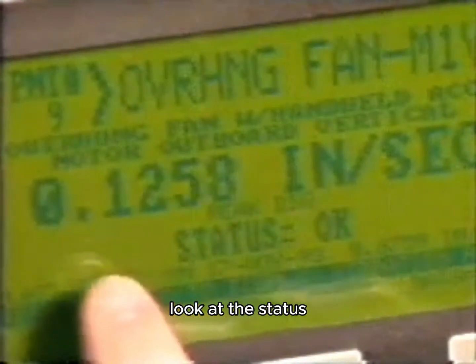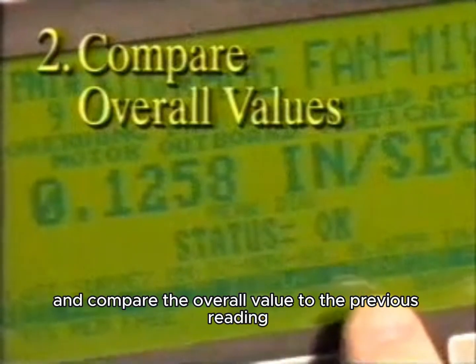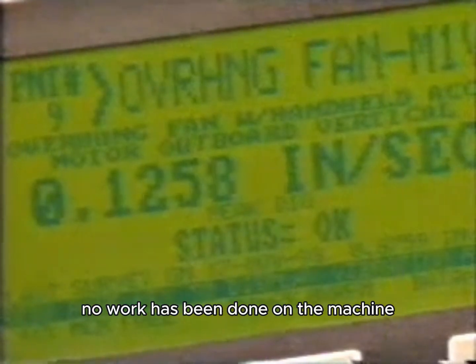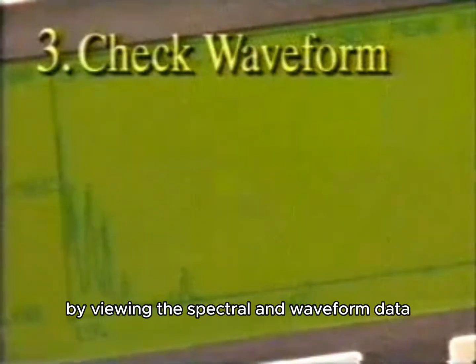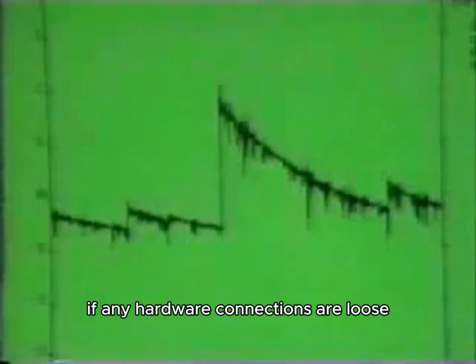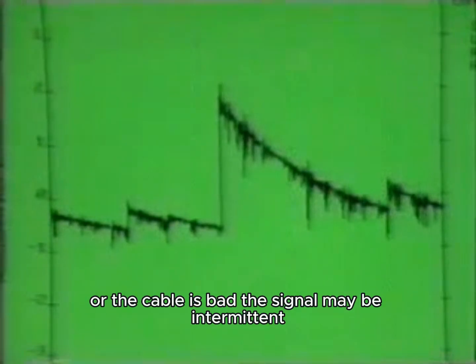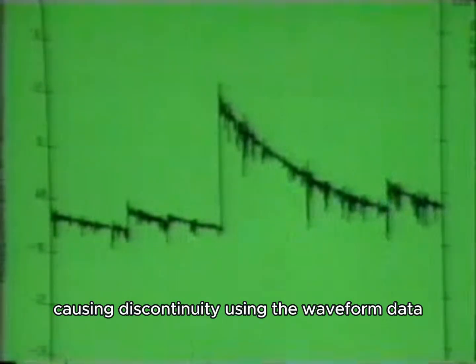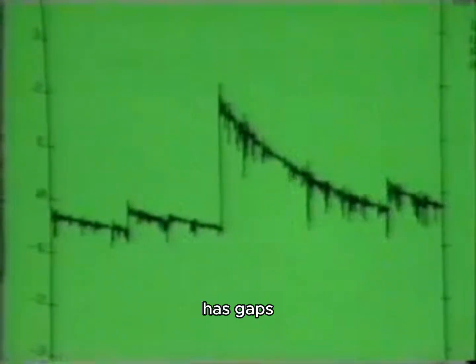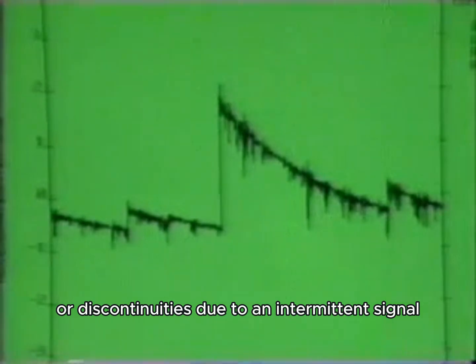Make the second check when a measurement point is complete. Look at the status and compare the overall value to the previous reading. The overall value for the previous reading is also displayed on the screen. If there is much disparity between the two overall values and you are confident no work has been done on the machine, then make the third check by viewing the spectral and waveform data, again looking for disparities. If any hardware connections are loose or the cable is bad, the signal may be intermittent, causing discontinuities in the waveform data. This waveform is typical of data that has gaps or discontinuities due to an intermittent signal.